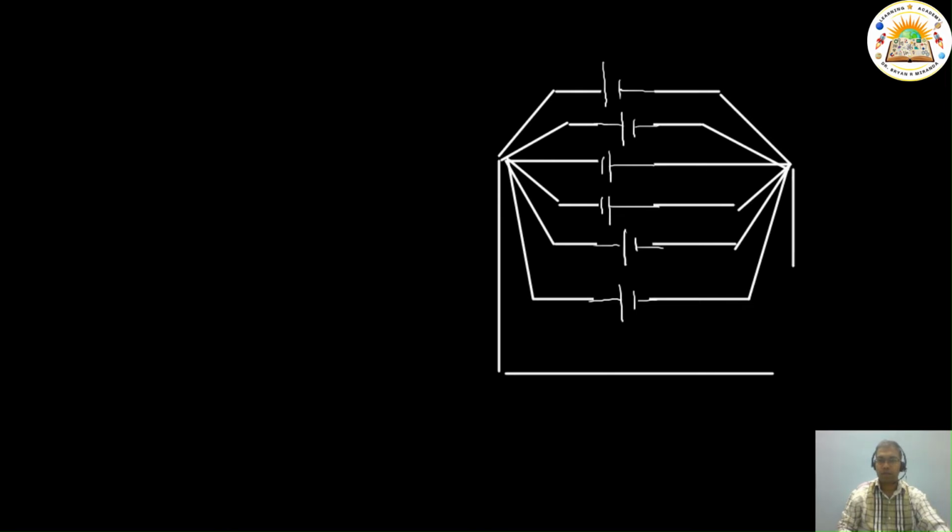Now in this case, if we see, we know that even if I connect this entire thing to a net external resistance, there is no way that my circuit is going to function in the intended way, because we have got two cells that are mixed up. So it is these two who are mixed up, this and this, whereas all the others are proper.